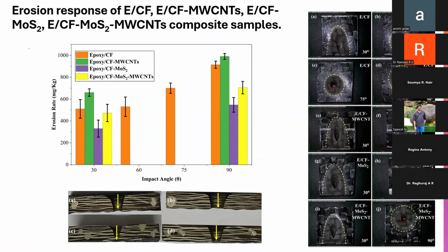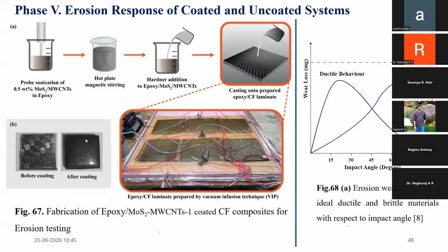In carbon fiber composites, maximum erosion happens at 90°. In a nanocomposite that does not have carbon fiber, it is at 15°. Nanocomposites actually show better properties than carbon fiber. When you think carbon fiber is going to give you big mechanical properties, it has almost 10 times lower erosion resistance. So all these problems are arising, and this is a simple setup.